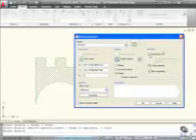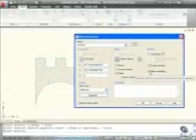We're not going to make it annotative, but we are going to scale uniformly in the X and Y directions when the block is scaled. We're also going to allow exploding. When you explode a block, it explodes it back into its original objects. That way you can explode a block, make some small changes, perhaps create a different block, a revision B or a revision 2 of that block.